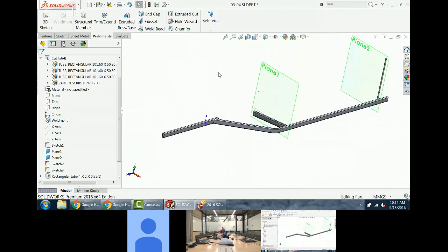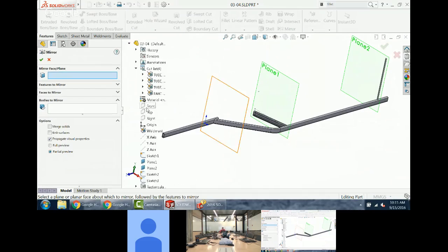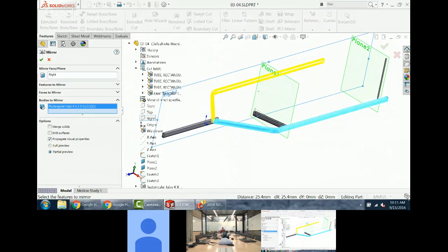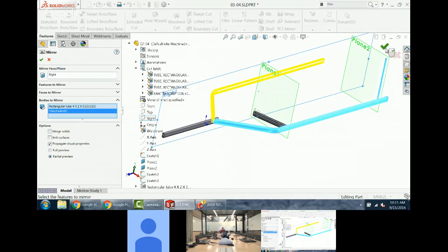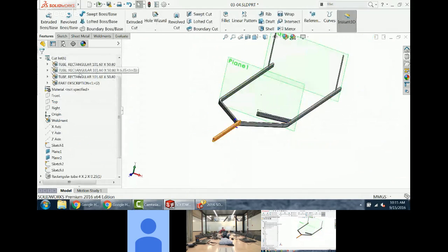All right, this is not looking like a boat trailer yet. It certainly needs more stuff on the other side. I showed you earlier that we can do bodies to mirror and mirror items to the other side. When you do a mirror like that, just the regular out-of-the-box mirror, it keeps them separate.